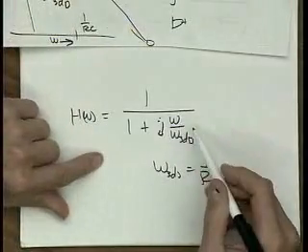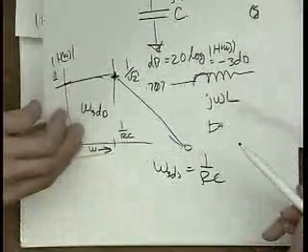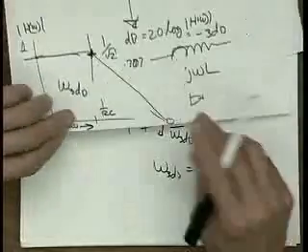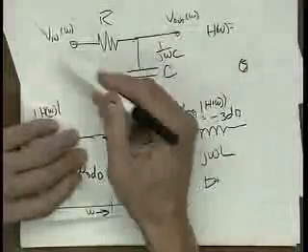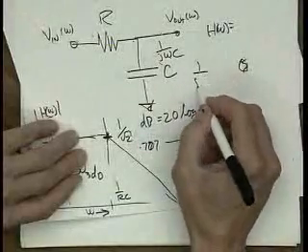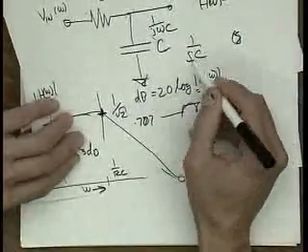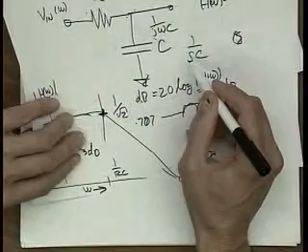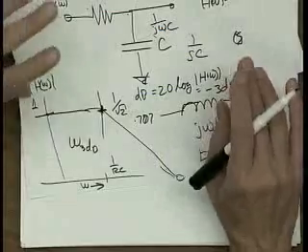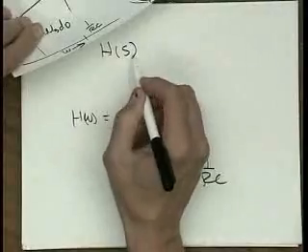And what we could also have done, instead of working in this Fourier transform domain, is work in the Laplace domain. Now here's a big step, and I'm not going to be very rigorous about this, but if we went in and calculated the Laplace transform of this same circuit, then instead of using 1 over j omega C, we would use 1 over sC, and s is the Laplace transform variable. Why would you do this? This allows us to calculate the response to any arbitrary waveform, okay? Though we hardly ever do that. We only worry about sine waves. But if we wanted to, we could calculate the Laplace transform of this thing. But we kind of know how to get to it.